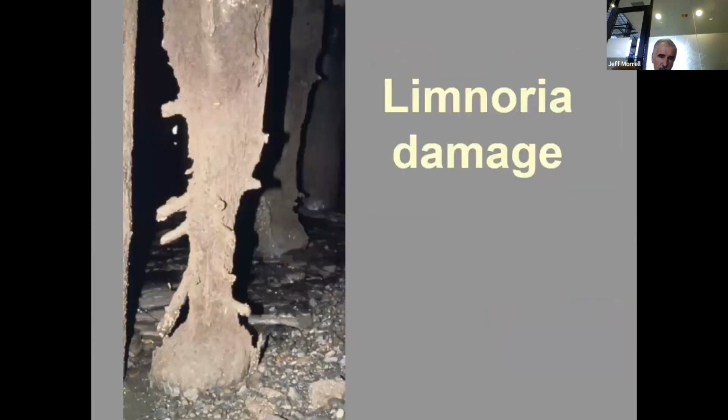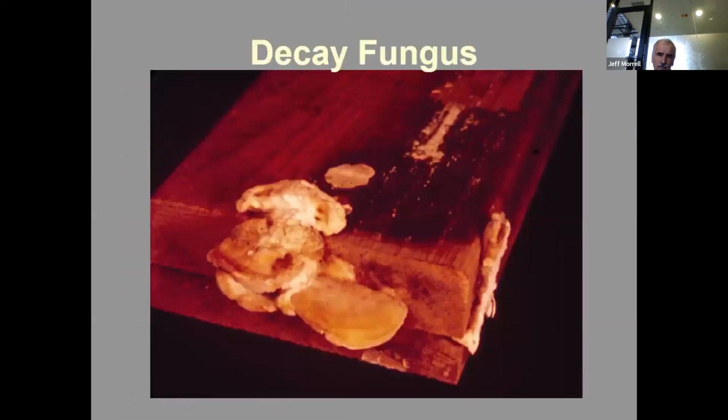So what you often see is the marine borers will damage the surface of the wood. The wave action will wear away that wood. It'll expose new wood, and the marine borers are going to say, I don't want to be eaten, so they'll tunnel further in until eventually you see something like this hourglass shape about the tidal zone, and then eventually the wood will fail. All of these organisms have evolved to live in salt water, and they're really important in recycling nutrients in the sea. So they play a real good role unless it's your timber that they're attacking. And they can all be protected by using either naturally durable timbers or using preservative treatments.